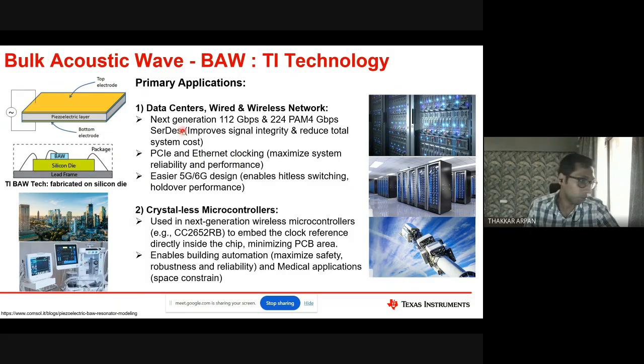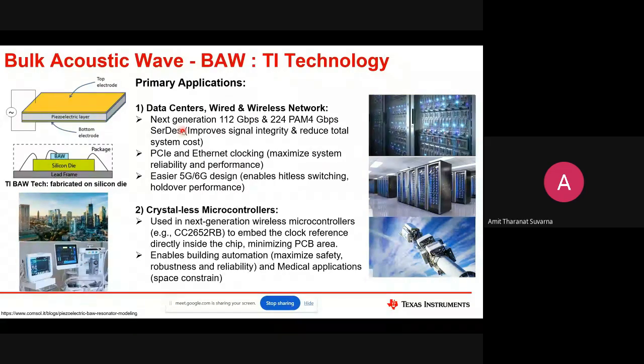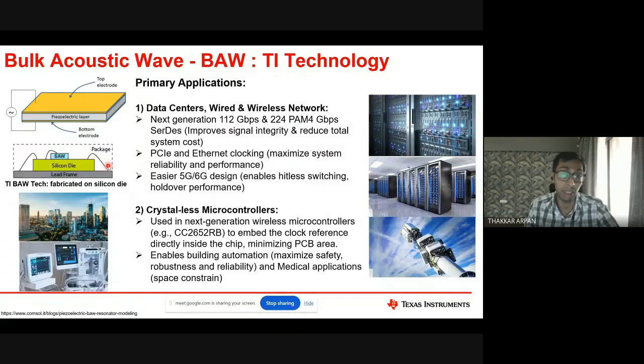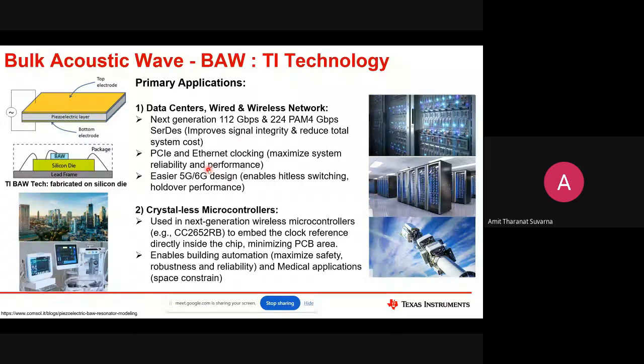Okay. So that remains a challenge. So I cannot say that the spur is not going to come on the other channel. It will come, but it will be within the spec. Let's say we are specifying that it will be less than 50 dBc. So for the applications where 50 dBc is not tolerable, you cannot use that part. You have to use two different dies. Filters we have to use for those.